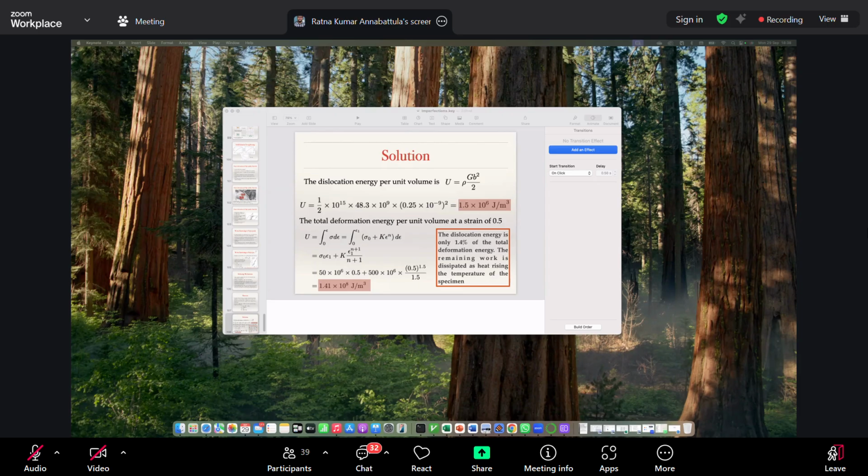Okay, and then we've also talked about solid solution strengthening, and any other foreign material that is sitting in the crystal will offer resistance to the dislocation motion, and that increases the strength of the material. And in the end, we also said that, okay, strengthening is quite common, but sometimes you will also see softening, and there are different kinds of softening responses. One softening could be due to damage accumulation, wherein bonds are permanently broken. And the second one could be geometric softening.